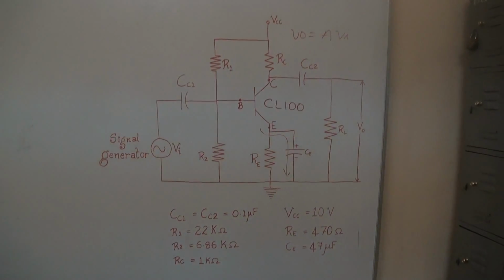So this CE amplifier is a low signal amplifier. So it requires input voltage in millivolts. We have to take approximately anything between 10 millivolts to 15 millivolts, depending upon the biasing arrangement we are going to provide to the circuit.